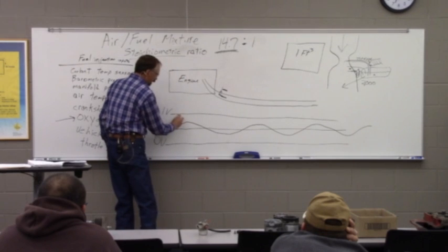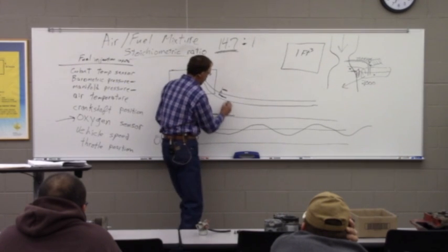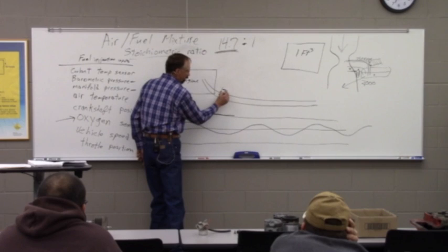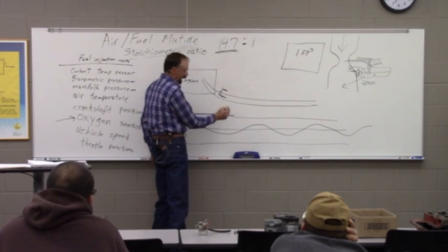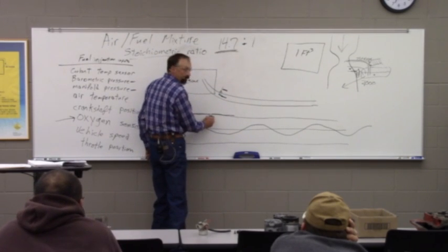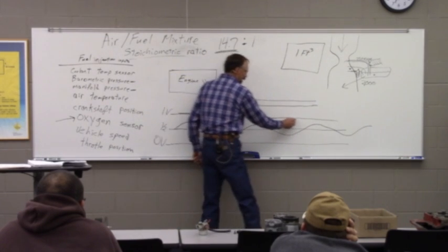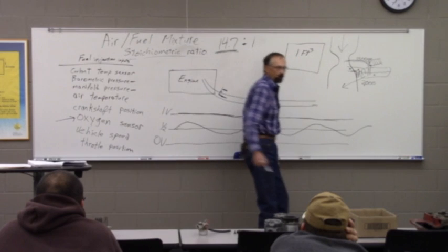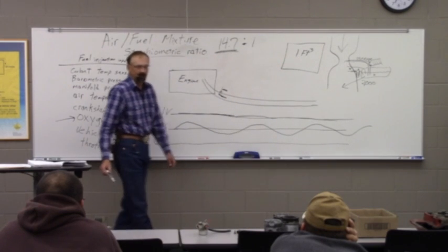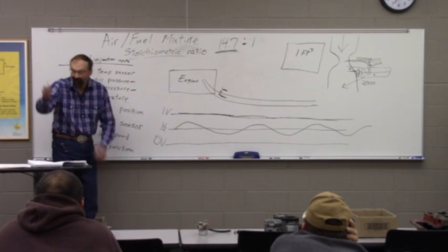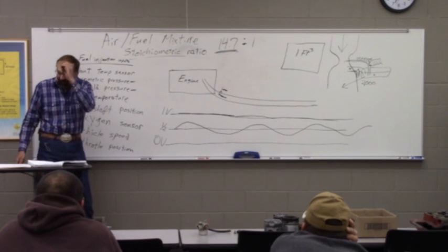So we're going to see 1 volt all the time because the difference in oxygen between out here and here is high. So when the difference is high, it makes 1 volt, and it'll just stick up here. So how many cross counts do we have there? A big goose egg, right? Yeah, that's what you were showing me, huh?